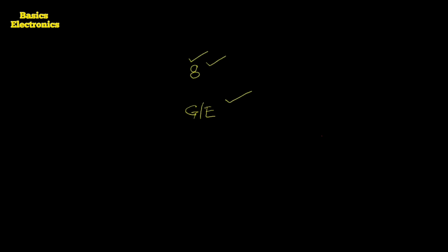So when this strobe input is equal to 1, it means the demultiplexer is in disable condition. When this strobe input is equal to 0, it means the whole demultiplexer is in the enable condition. Okay, so there is enabling and disabling. The demultiplexer is in active mode or in deactive mode. That depends on this input, and this input we call a strobe input. Okay, now after this we can write down the construction.